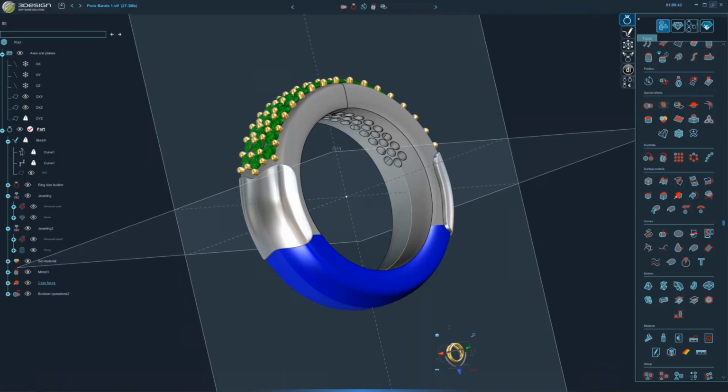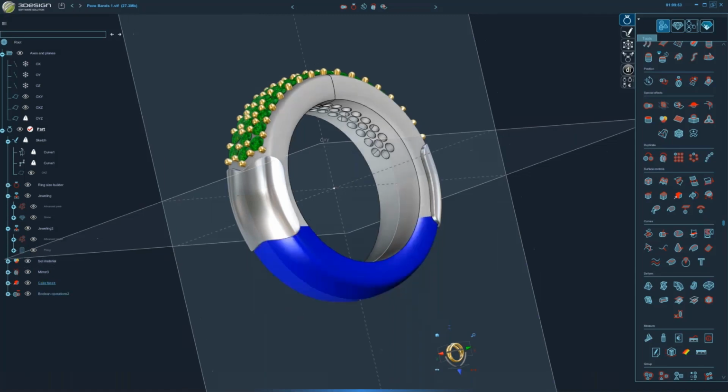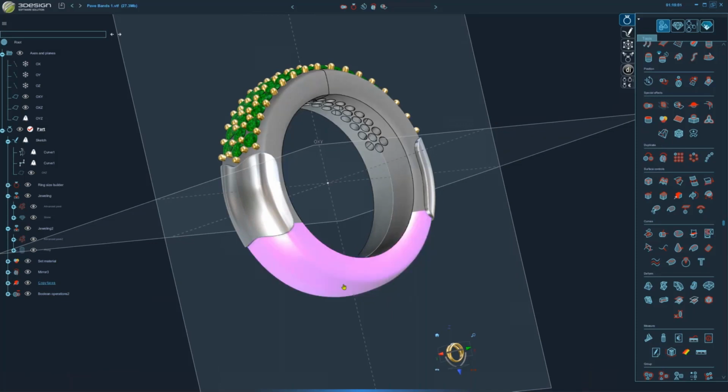Be careful with faces when it comes to history. They can get a little weird. It was still trying to reference before I cut it because of the way I undid it out of order there. So it's good for you guys to see. Sometimes it's best to undo the steps and just redo them if you need to make a change like that. Did not like that at all. Okay, so now we've got the part that I want to unwrap.